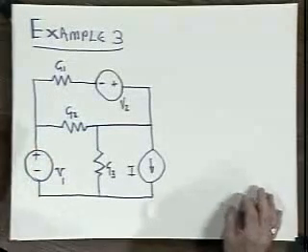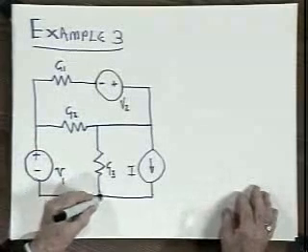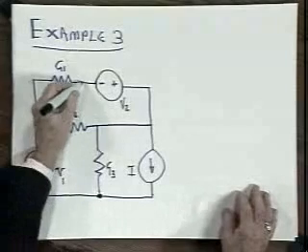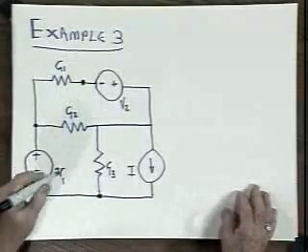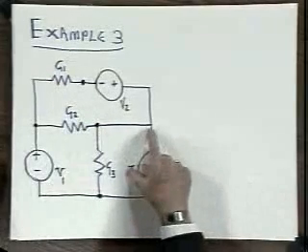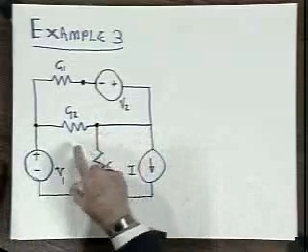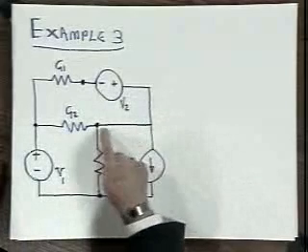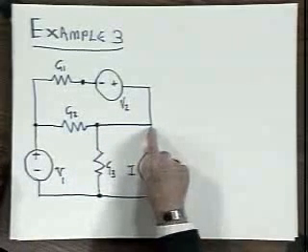That is, if we label nodes here, here's one, here's another, a third, and a fourth. This is not a new node, okay? This is just simply the place at which elements G2, G3, I, and V2 all connect. Be wrong to indicate a node out there.